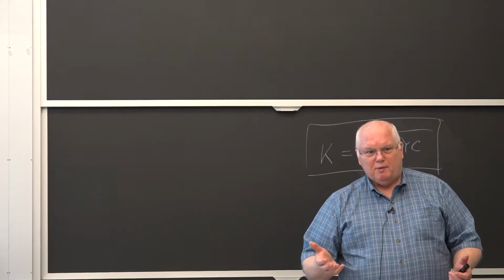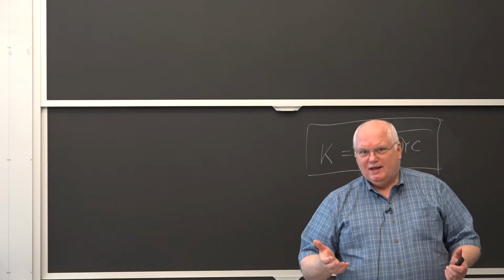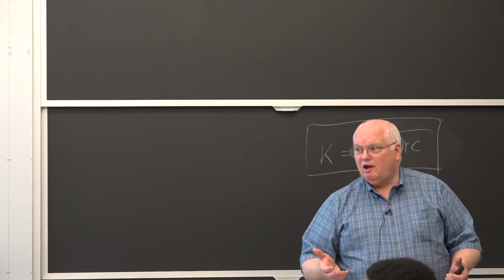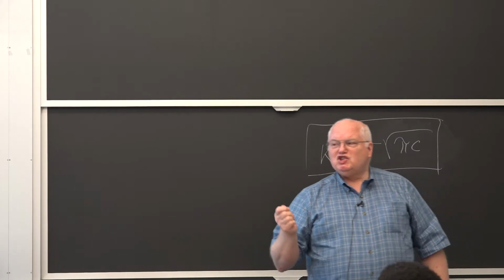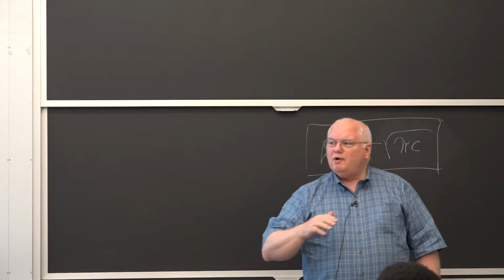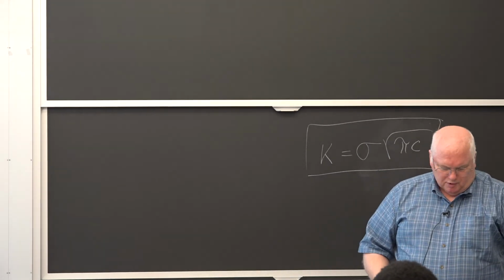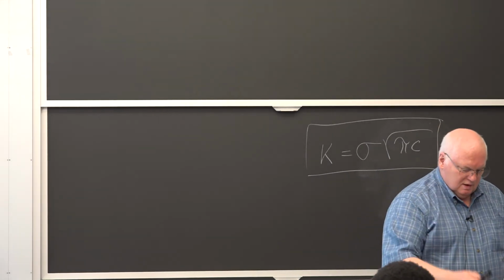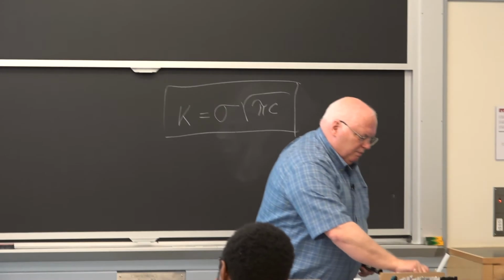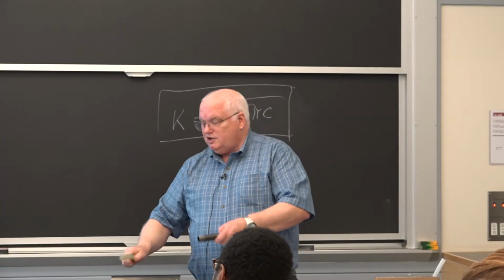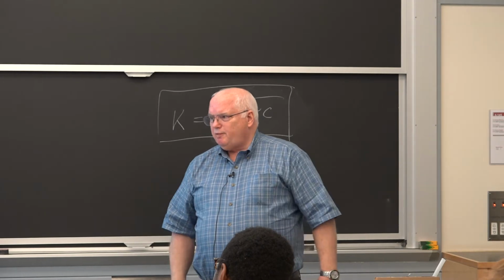Why do you use beryllium copper tools? They use it a lot in the mining industry. Fatigue? Pardon me? No, not fatigue. Turns out spark resistance. Copper has better thermal conductivity, so if I had 2 pieces of steel and I bang them together, I could get a spark.